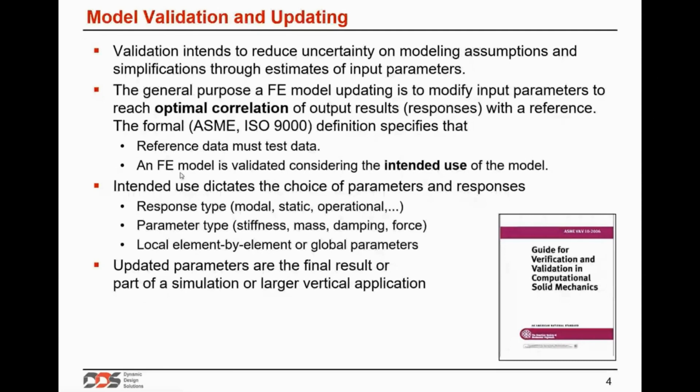It is important to consider the intended use of the model when doing a validation, because a model can be valid for static analysis, but not valid for dynamic analysis, for example, or vice versa, because the complexities of the model can be different depending on the application.